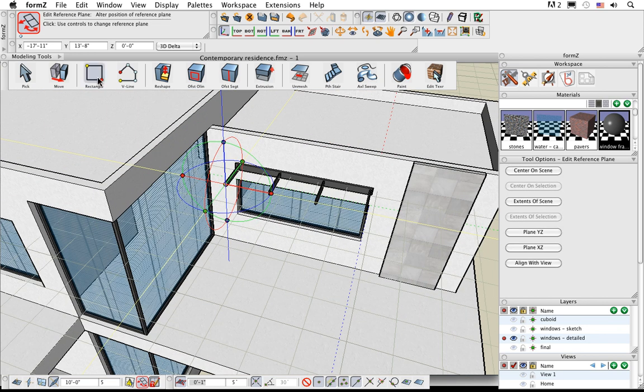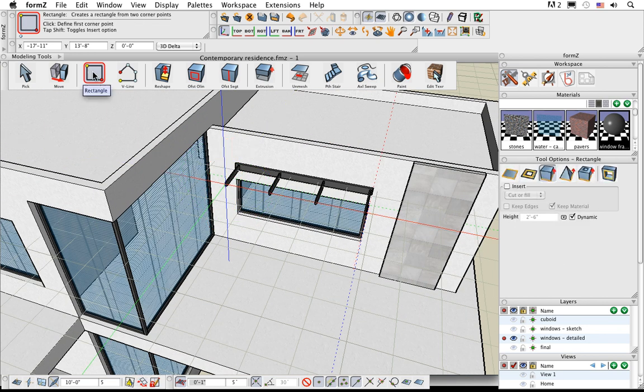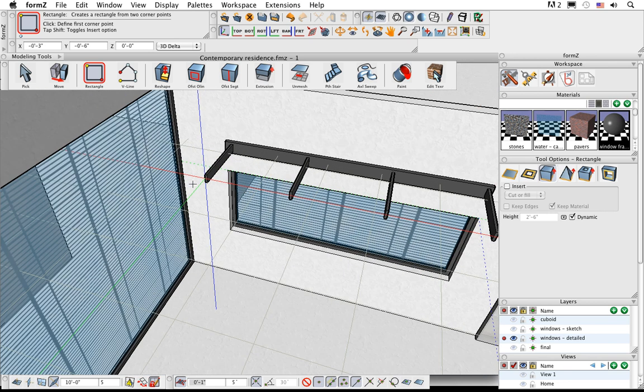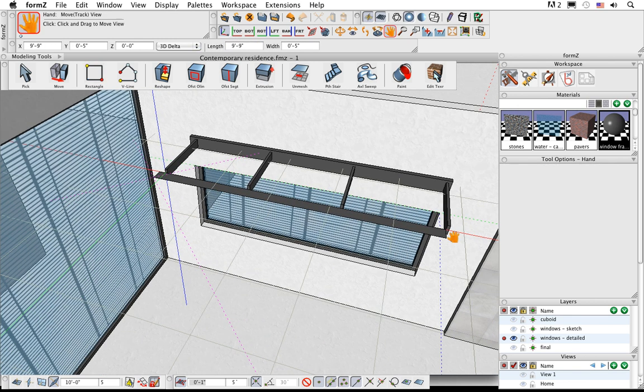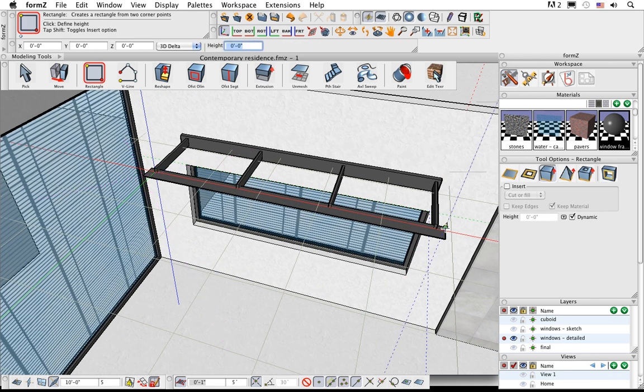So now if I were to zoom in here, select one of the drawing tools, if you want to lock it right there, you hit the F5 key, that locks the drawing plane. So as I move my cursor, it's no longer changing to snap to the faces, it's locking to the current active plane when I hit the F5 key. So now I can very easily draw anywhere. You can see here, I'm not snapping to any existing geometry, I'm drawing right on that plane somewhere in 3D space. So I can quickly draw that exactly where I want that piece to be.